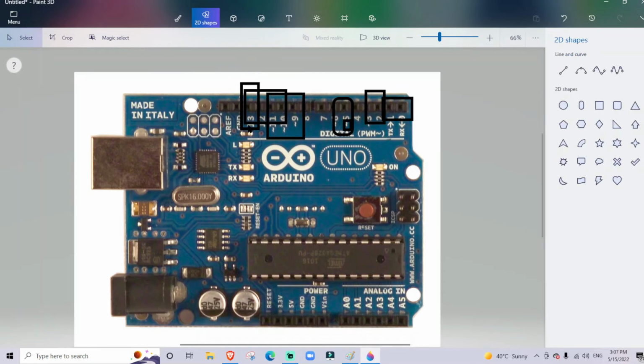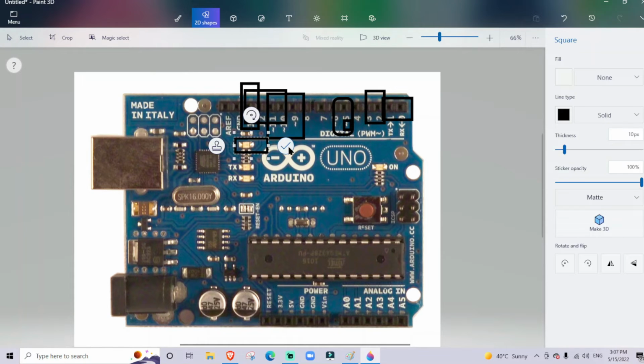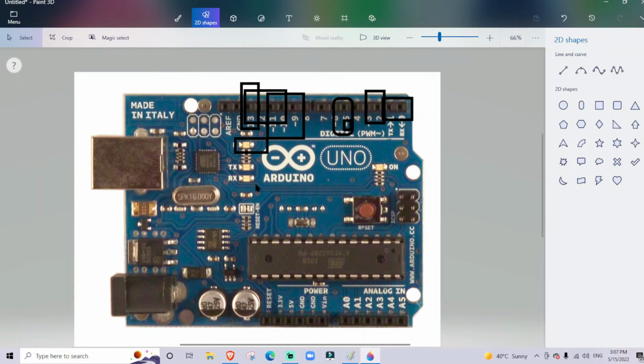Now LED pin number 13. There is a built-in LED connected to digital pin 13. When the pin is high, the LED is on. When the pin is low, it's off. The built-in LED on pin 13 is used to show when the onboard ATmega328P bootloader is running, usually when the Arduino is starting up.